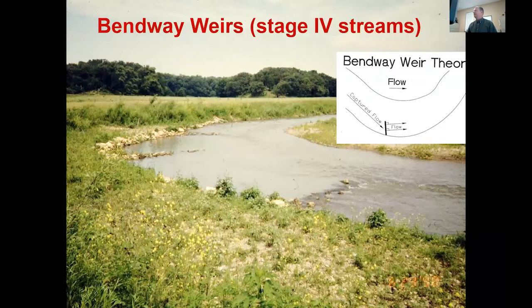Benway Weirs we don't use too often anymore, but their purpose is similar to stream barbs. They have a flatter crest, and they capture flow behind them and release that flow at a perpendicular direction to the Benway Weir. So they're put in not at a 90-degree angle, but just tilted slightly upstream so they can angle the flow away from the bank.